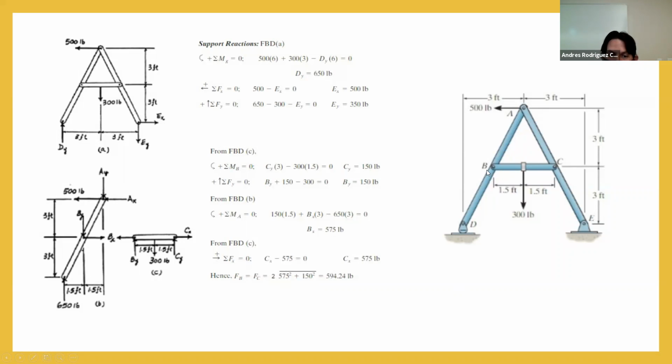So to obtain the force in the element, or the internal forces at this point, we have to use the Pythagorean theorem. This one is wrong here, it's just the square root, but we have to do the Pythagoras here, obtaining this value that we already have here. It's going to be the longitudinal one, because we got two elements, X and Y. After that, as I told you before, we have a situation with a two-shear plane. So we have to divide this resultant force by 2, right? So we got the shear force in here, and then we can obtain the stress.